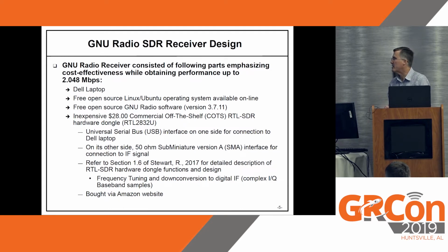Has a USB interface on one side to connect to the laptop, has an SMA 50 ohm interface to connect to the IF signal. And the dongle does the frequency tuning, and it also down converts to digital IF, which I sometimes call 0 hertz IF. And I just got that on Amazon.